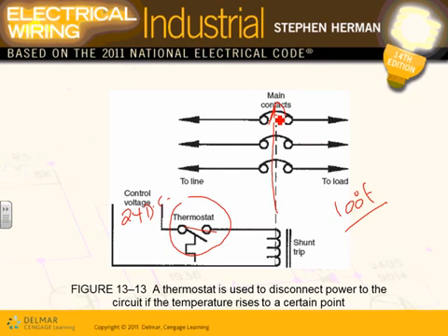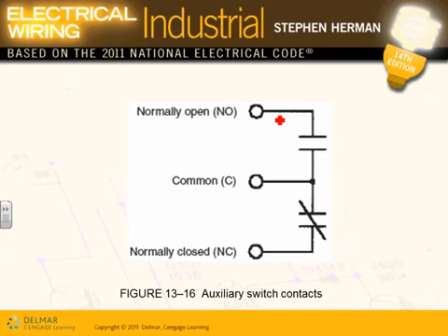Shunt trip. You're going to hear this one all the time. When you become a project manager and you lead your own project, you're going to hear shunt trip. Hopefully you remember one day we talked about shunt trip. Big deal. So did you guys hear it now? The shunt trip is just a little coil you energize to trip the circuit breaker remotely before a predetermined value.